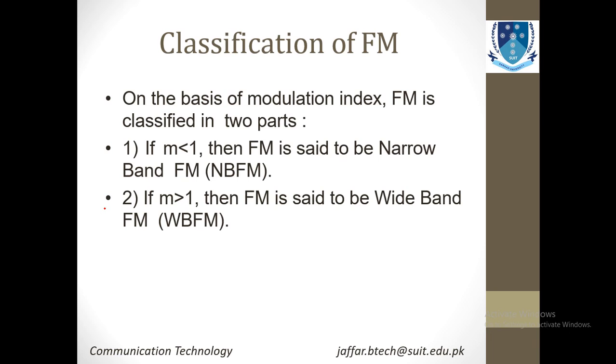Now let's talk about the two major classes of FM. The first one is known as NBFM, that is narrowband frequency modulation, and the second one is known as wideband frequency modulation. Just to elaborate simply, if the modulation index is less than 1, your FM is said to be NBFM.